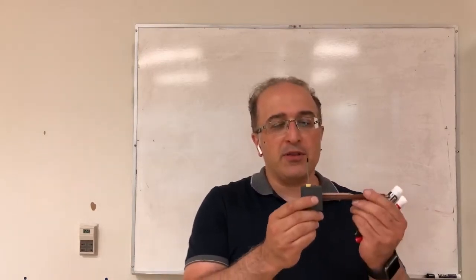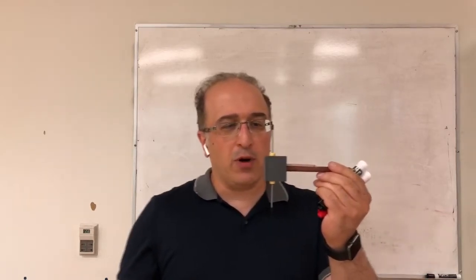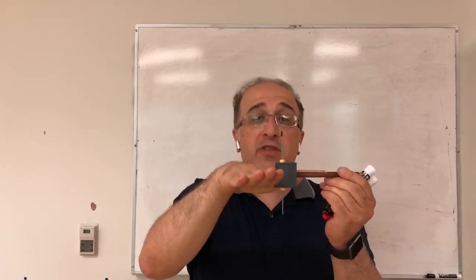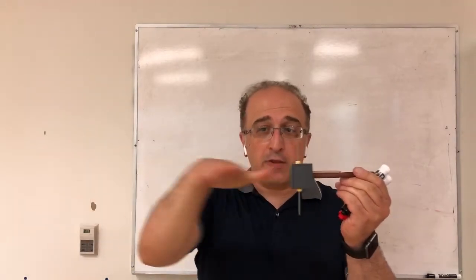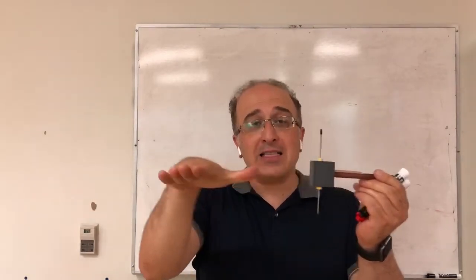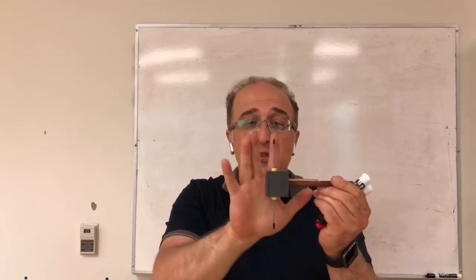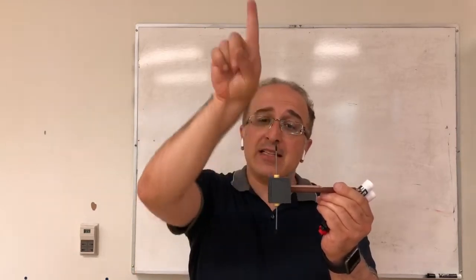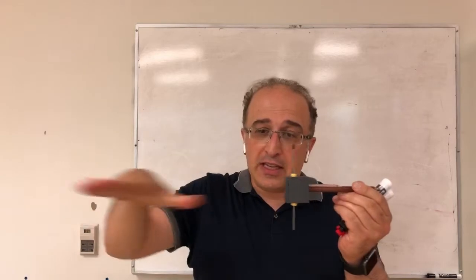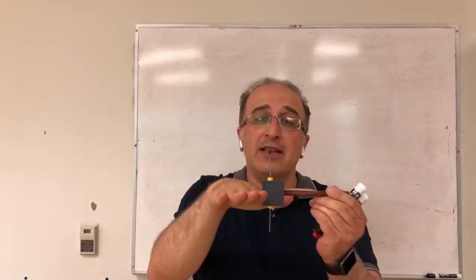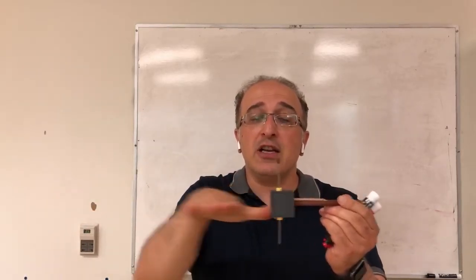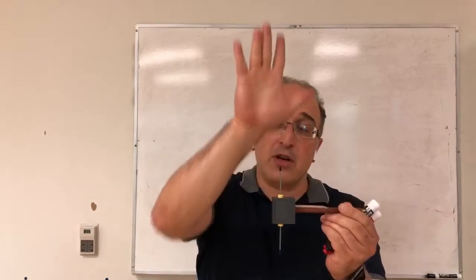So for example, if this is your dipole antenna, one of the cuts that you might like to know the measurement for is the horizontal cut, right? Or we may call it azimuth cut. So this cut would be essentially azimuth cut or horizontal cut. So if this is my z-axis along the antenna, the plane that I want to know the radiation pattern for is essentially the xy plane because this was z.